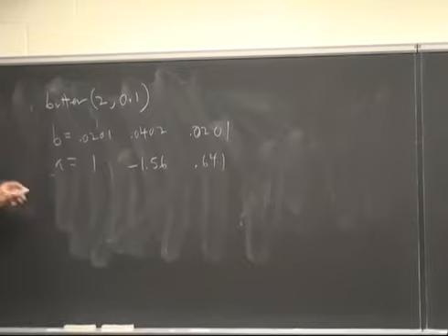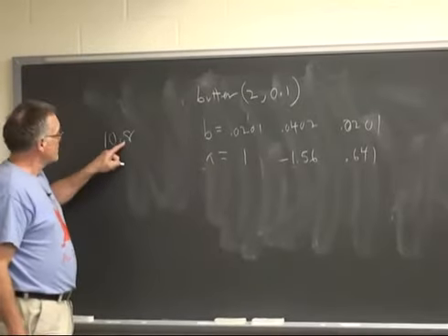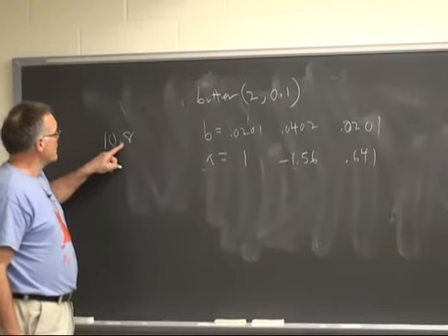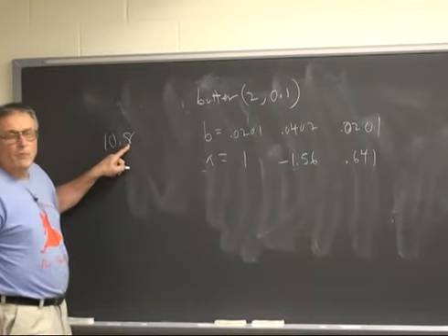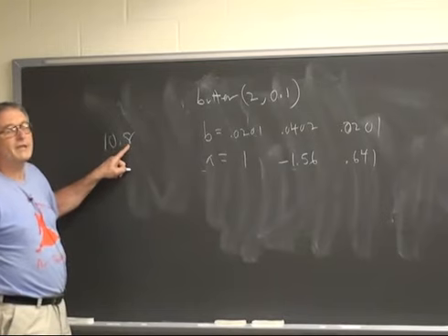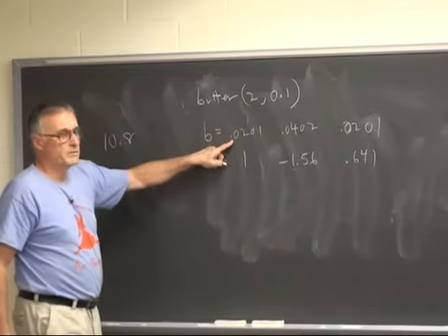So if you're only maintaining a 10.8 filter, and you call the fractional size 0.02, then you only have 1 or 2 bits of accuracy left to represent the 0.02.